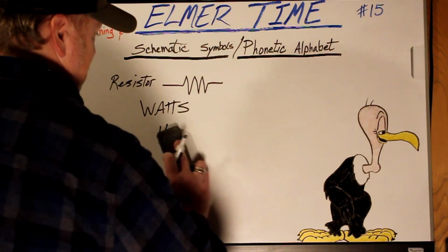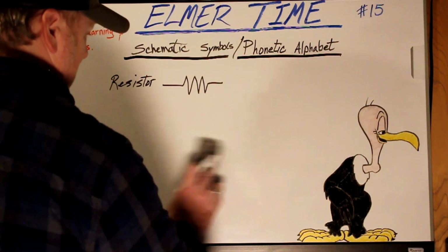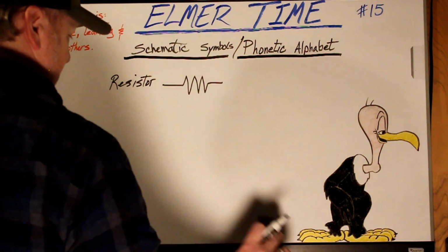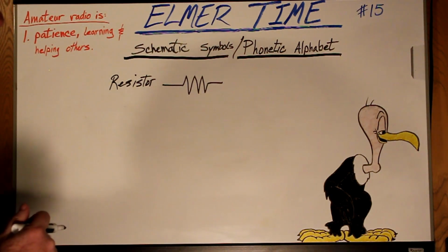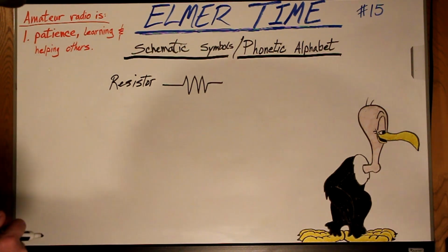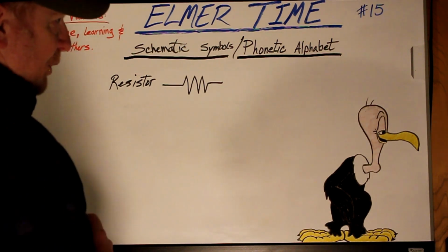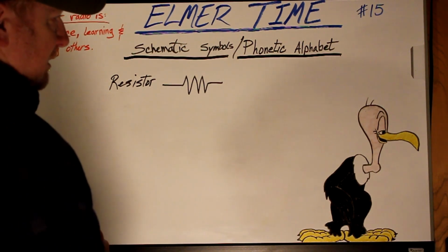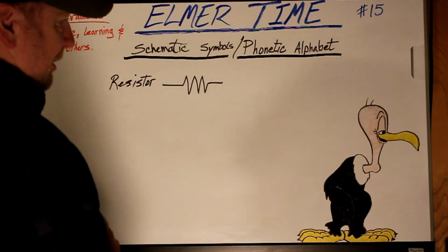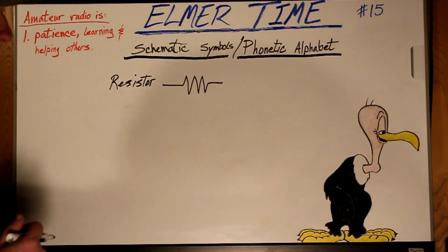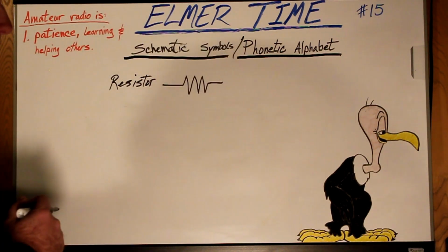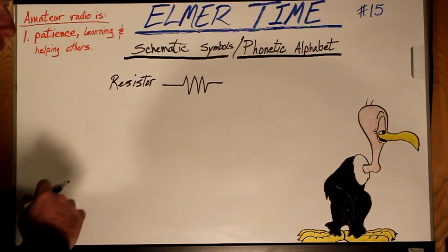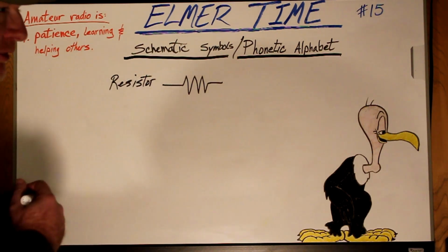But pretty much all resistors, when they limit the current flow, the product is that it generates heat. So resistors have to be rated appropriately for the circuit. If they're the incorrect wattage for the application and it's rated too low, that resistor can burn out.